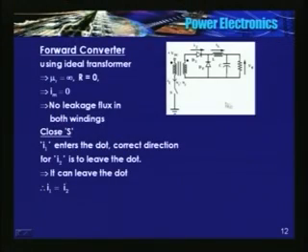See the diode here. So the path is something like this: diode, inductor, output, capacitor and load, back to the secondary winding. So what is the primary current? It is the equivalent secondary current. I1 is equal to I2 prime, because Im is 0, no magnetizing current.